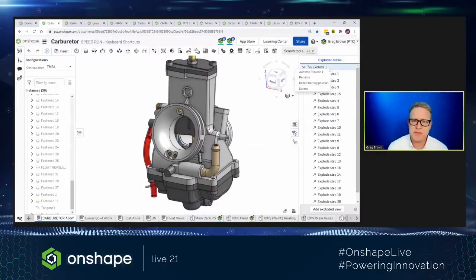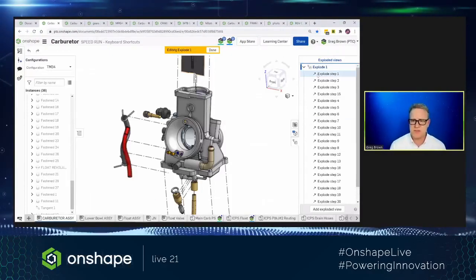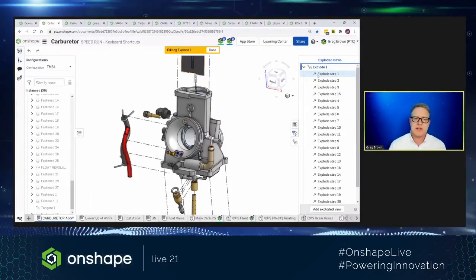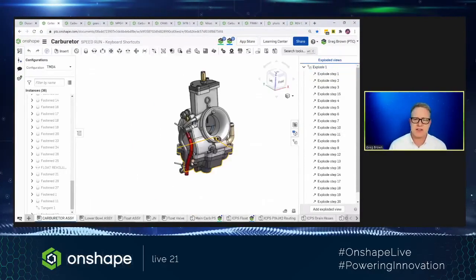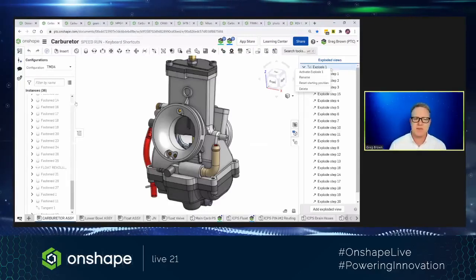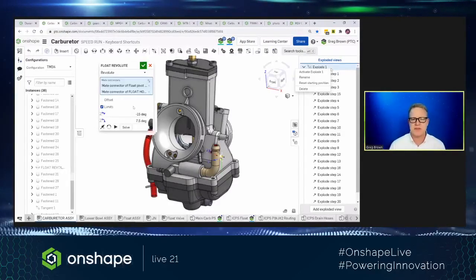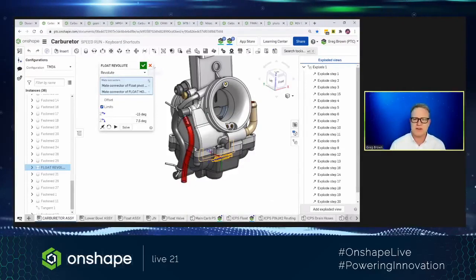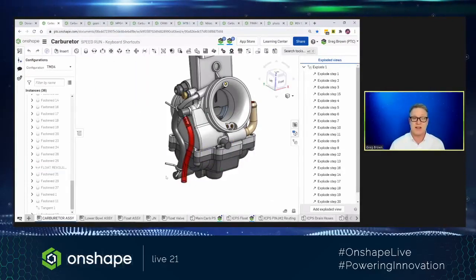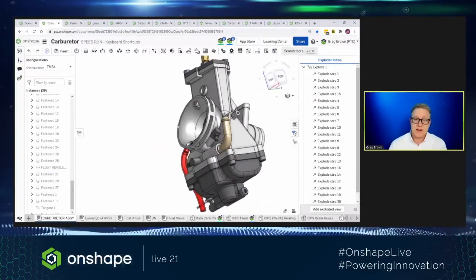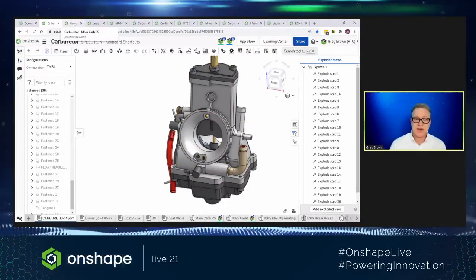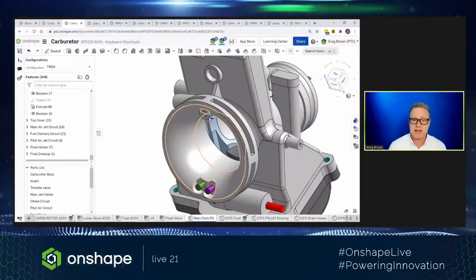At the end of the day, pretty much everything we design consists of more than a single part and needs to be assembled, and Onshape's mates are used to do that. Onshape's unique method of mating components means that parts that may have needed 2 or even 3 separate constraints in a traditional CAD might need only one mate in Onshape. The secret to Onshape's mates, of course, is the mate connector.